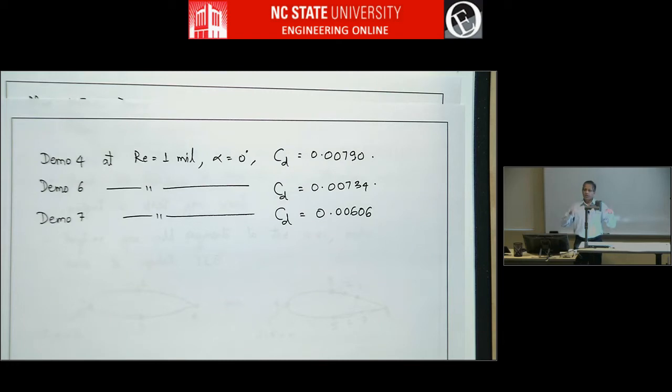Run Xfoil again and say, now I think I'm in the right direction, and then do more of that. And at some point you'll hit a wall, like whatever change you make, you won't be able to decrease CD. And then at that point you say, that kind of design thinking is done. Maybe I should try something else, or maybe time is out and I'm going to say this is my final attempt and finish it. Okay.